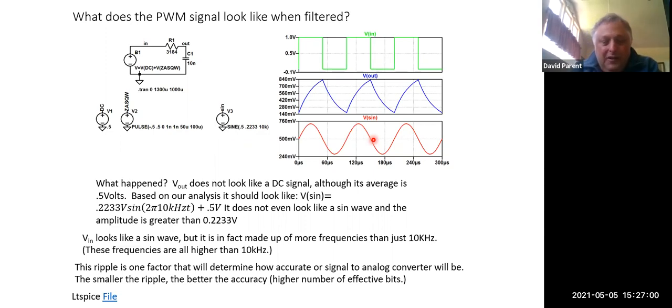And so even though you might have a gain bandwidth of an op amp of 1 megahertz, divide that by 50 to get the maximum square wave frequency so that you don't get the harmonics.